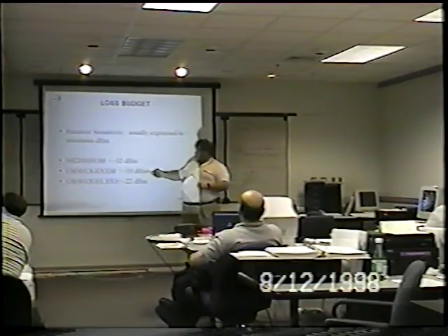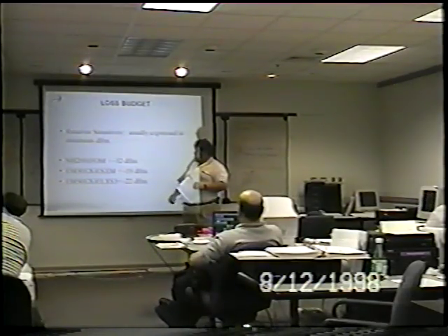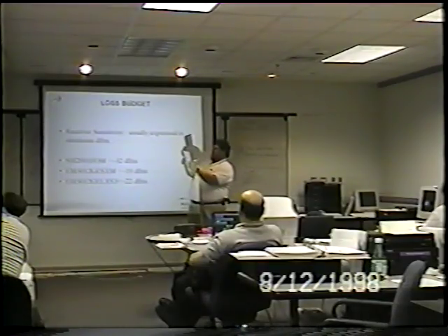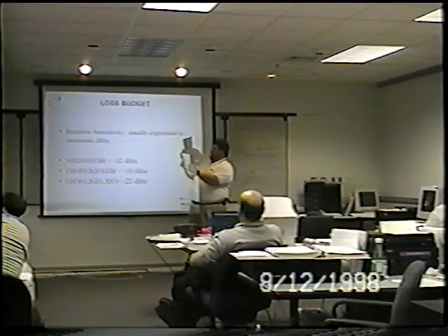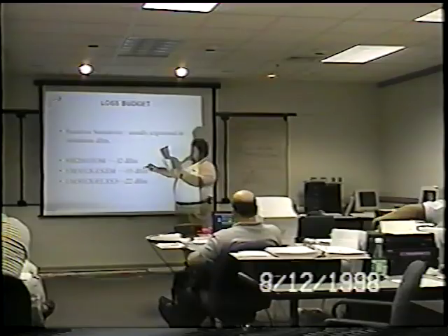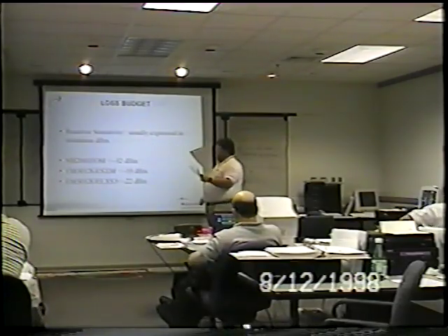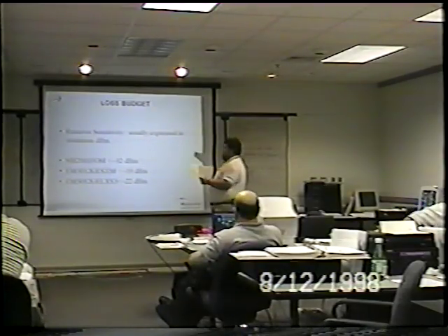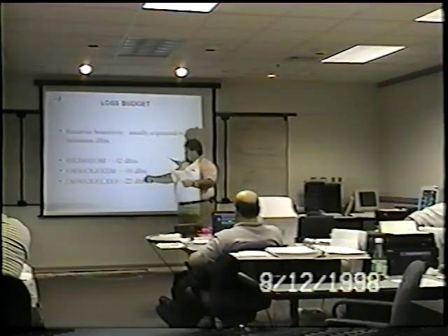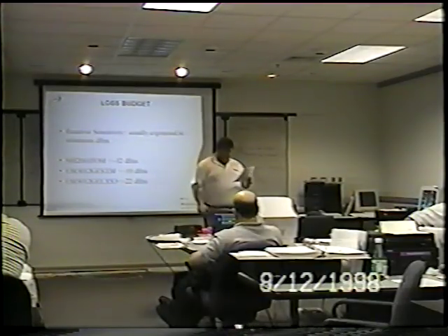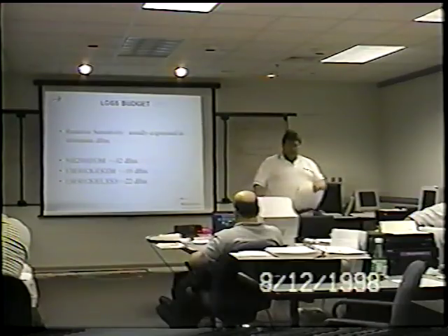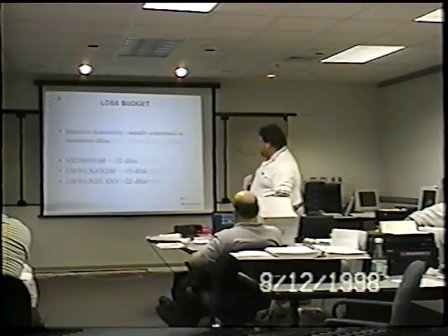If you take a look at the 3012 GESXM, I think there was a change there recently. GESXM, that might be a boo-boo. We'll just say it's minus 19 for now. And then the 3012 GELX S3 receiver is sensitive down to minus 22 dBm. Those are some typical numbers you see in receiver sensitivities.